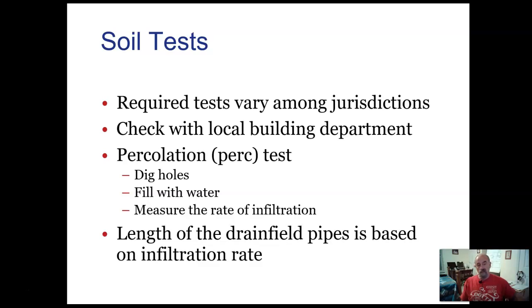Some soils can't adequately accept or treat wastewater, especially here in North Carolina with the clay. That does not work well at all. Most jurisdictions require that the soil on which the septic system will be built is evaluated to make sure it can provide adequate treatment, and you should check with your local building department to determine how the soil must be evaluated. In some cases, local officials must perform the testing. Pretty much, I don't know of any municipal systems that don't have to do the test.